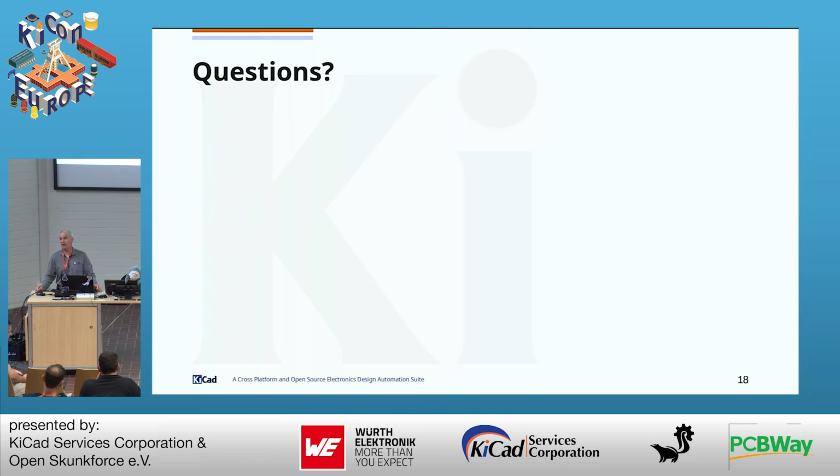But that's just really a view. It's not really a change to the board. So all the fields will change, like the value fields will change. But most people who use variants don't put a value field on a resistor because otherwise somebody's going to get confused. Let's say R2 is 7K, you put 7K there, and then one of your variants is 10K. Well, wait a minute. So you don't show the values on the silk screen, because as soon as you change the silk screen, that's a different board. So remember, one of the limitations of variants is it can't change the board. It can't make a different board.